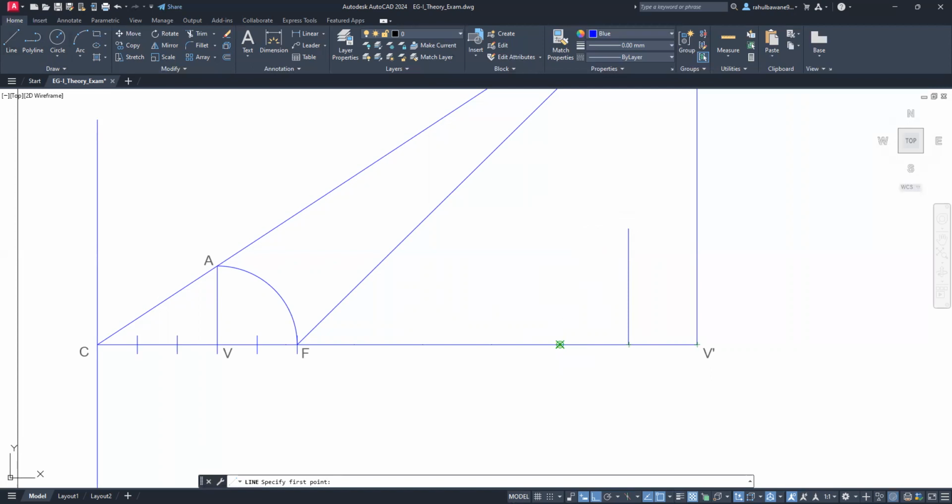This is the second line, enter, dragging to the third point, enter. Or as another option, I can pick any line segment, copy it, and drag from the bottom end. Along with the cursor, this line also comes with a circle, and whenever there are 7 division points they are shown by complete circles.